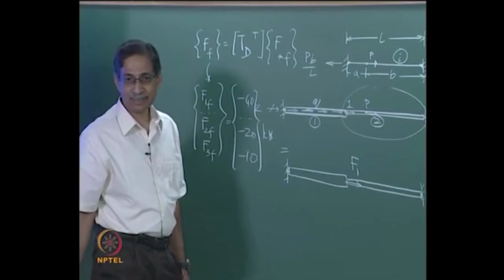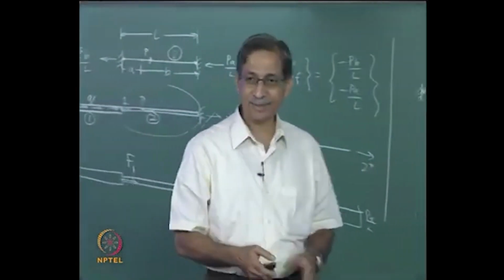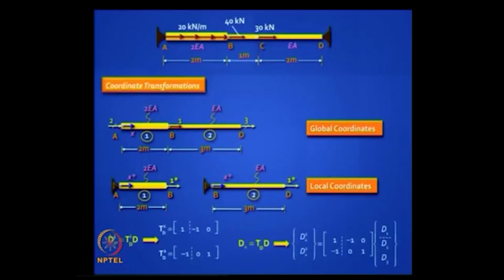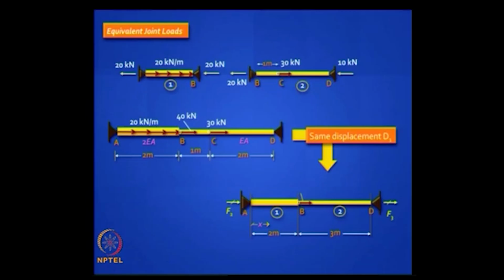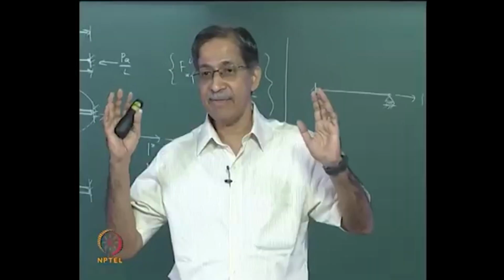Now remember, there was a nodal load in the structure. Let us go back to the original. Remember, there was a 40 kilonewton load acting at F1. So that you have to include. So you have to do it the good old way, and you will write it like this. So this is what we discussed. Manually do it. You will end up with the same displacements as you would get in the original structure, but now you also have to add FA, which is already there, so we will use that later. Finally, your net load vector is FA minus FF.